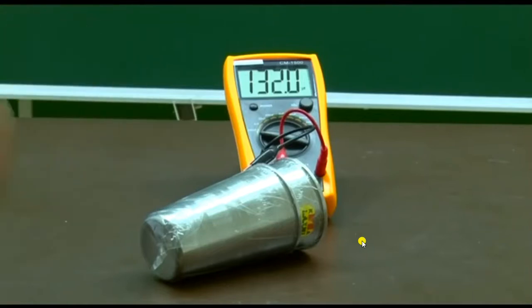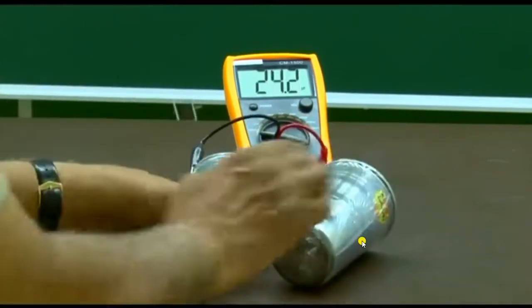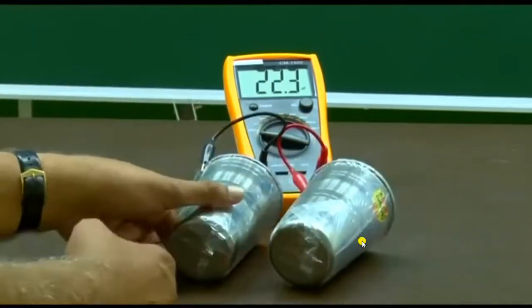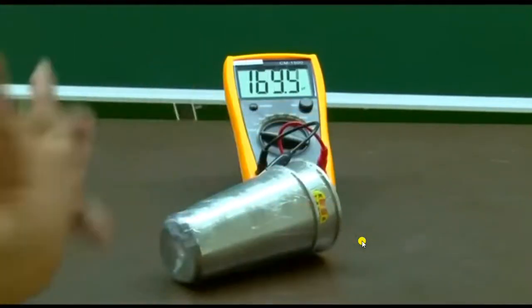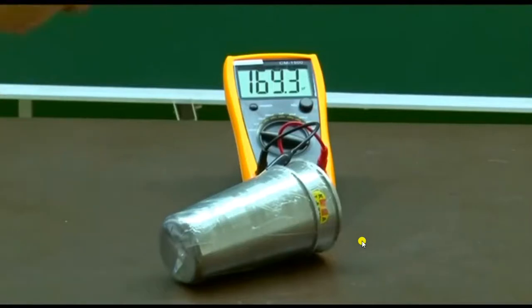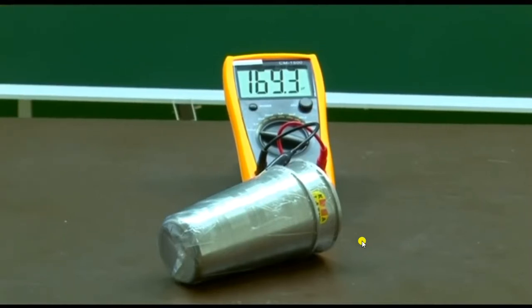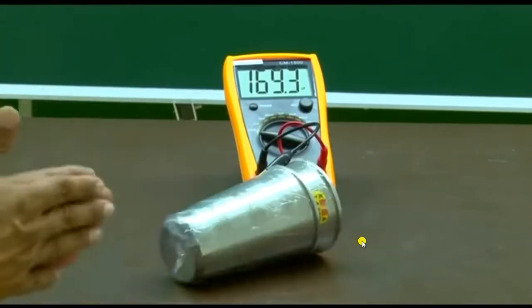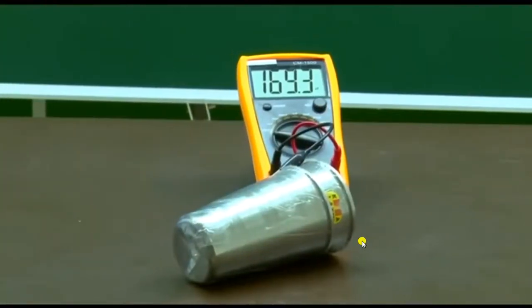So more and more area is in front of each other. That's the effective area. In fact, when I am putting it this way, the effective area is very small. The area which is facing each other is very small. When I am pushing it here, effectively the area which is facing each other is quite high. So your capacitance increases if the facing surface area is larger. And of course, the distance between the conductors, the average distance in whatever way you measure, is important.